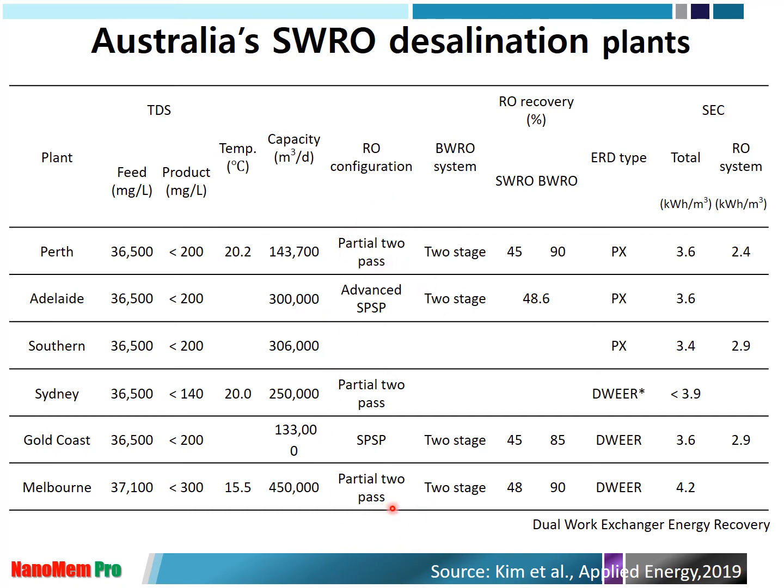This specific terminology is very relevant to first pass and second pass. First pass, I will talk to you about later. To improve the water quality, they utilize the first RO and second RO permeate. That's the reason why they can partially combine the first pass permeate with the second pass RO, or completely combine them together. So that differentiates partial pass and partial split pass. That's the little bit of difference.